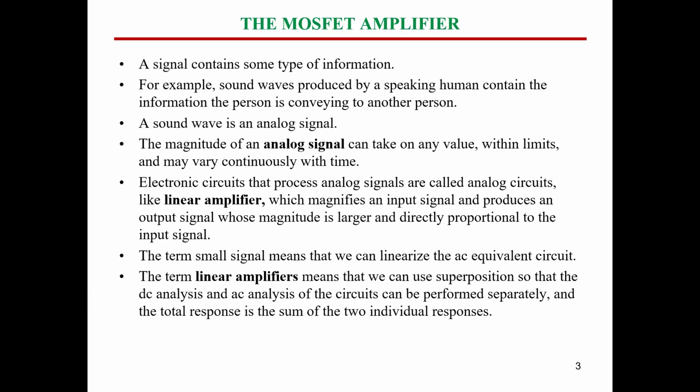Superposition, I think you learned superposition before in electrical circuits, and we will see the meaning of using superposition here in our small signal and in linear amplifiers to identify the signal parts and start amplifying a certain signal. So we have to use superposition here so that the DC and AC analysis of the circuit can be performed separately. So this is the concept of superposition.